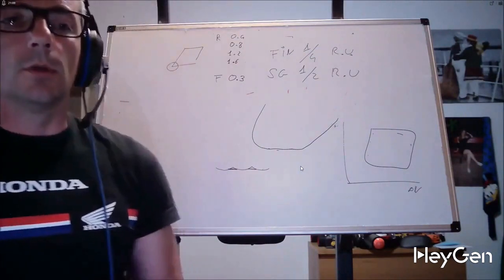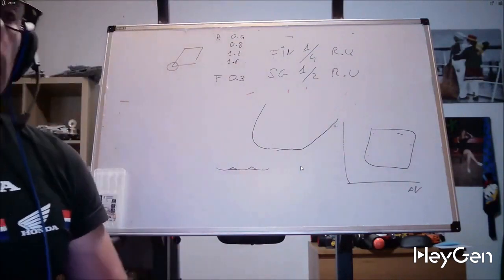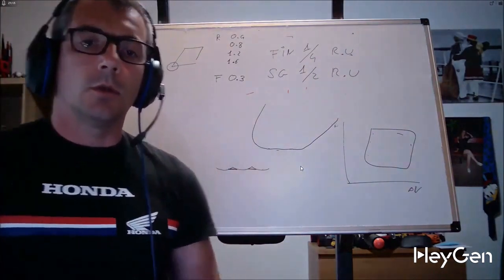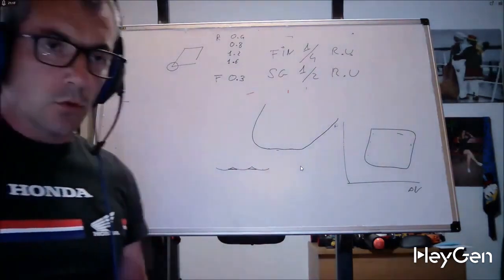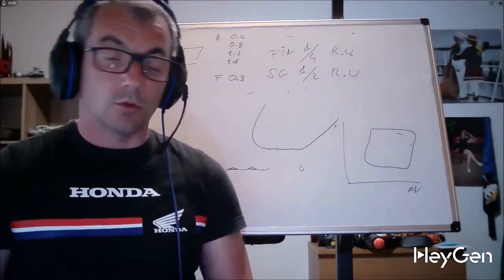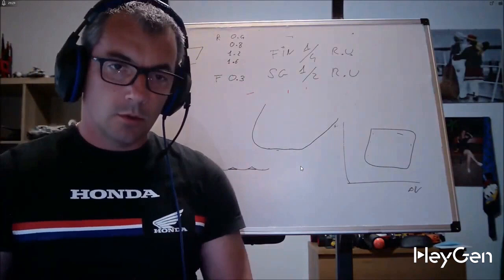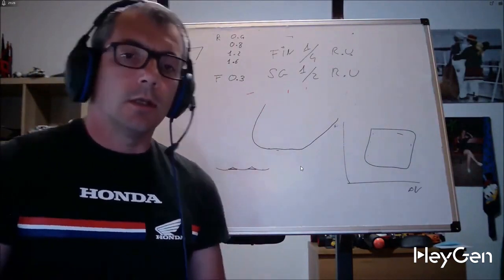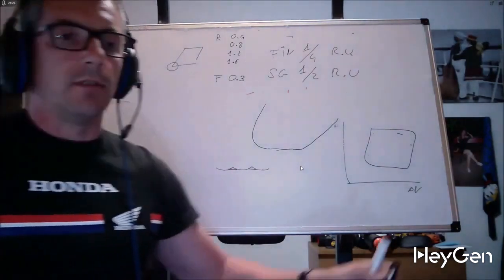Even there, the scraping tool can obviously generate vibrations. Sometimes it's fine, sometimes it's not. If you need to work with a material that requires particular chip control, it might not be suitable. What is chip control? It is ensuring that the chip breaks. I never want to see machines that produce chips 20 meters long.